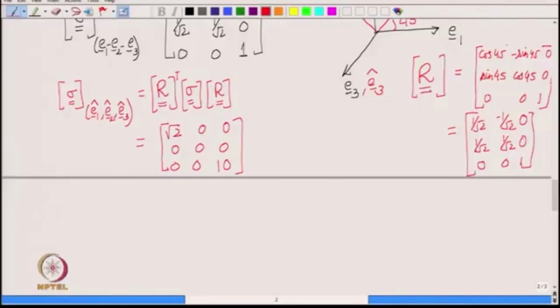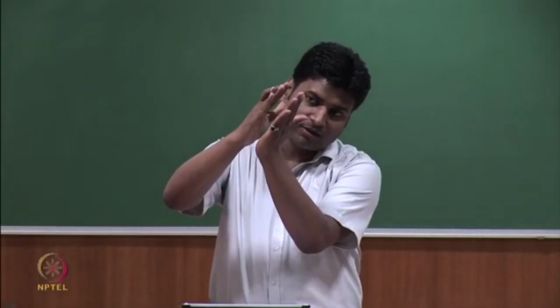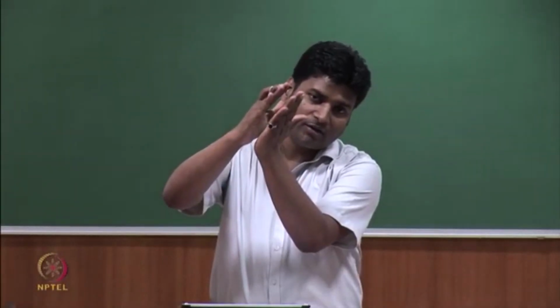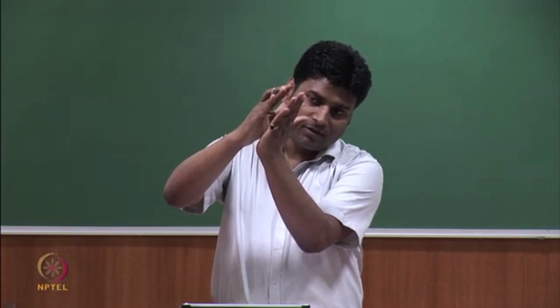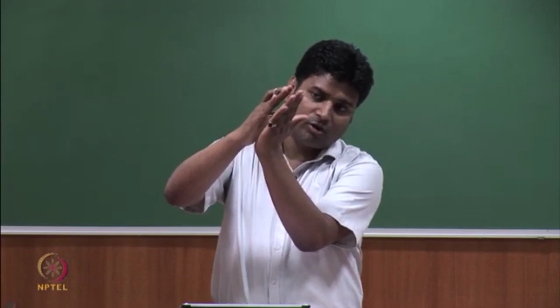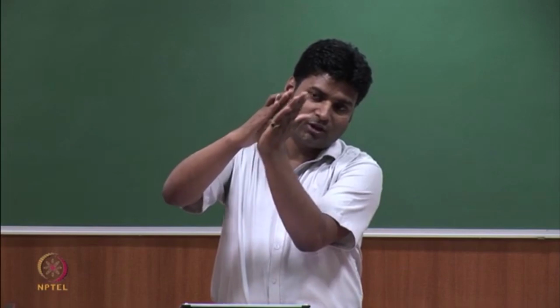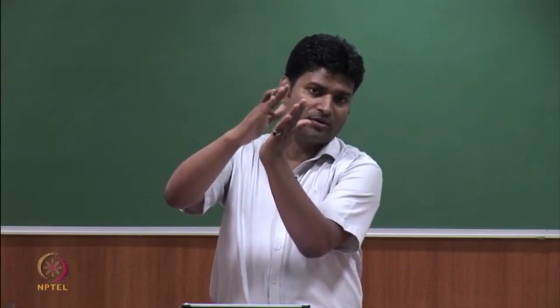All right. What about the first one? So, that is the traction on the E1 hat plane, and that traction has got only the first component, which is along E1 hat. So, it has only got normal component. So, if you again look at two sections whose normals are along E1 hat and minus E1 hat, then the traction between them is such that it has only normal component. There is no shear component, it only has normal component.